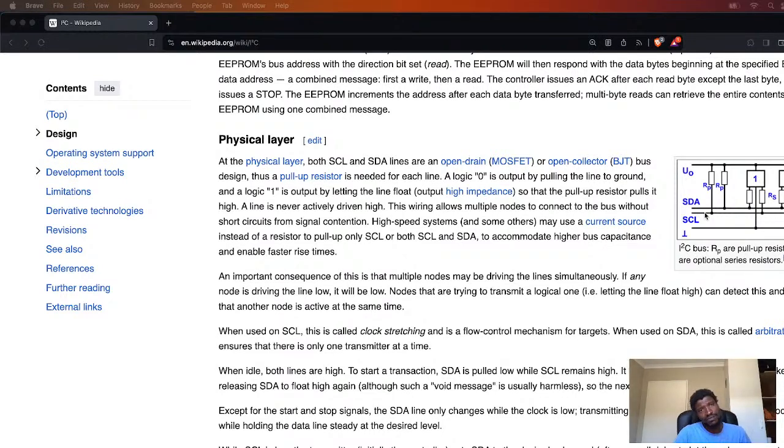So first of all, we've discovered I2C is much slower than SPI. So I2C would be used where speed is not a factor, and we want a smaller form factor because we want fewer pins, and possibly a multi-master environment.